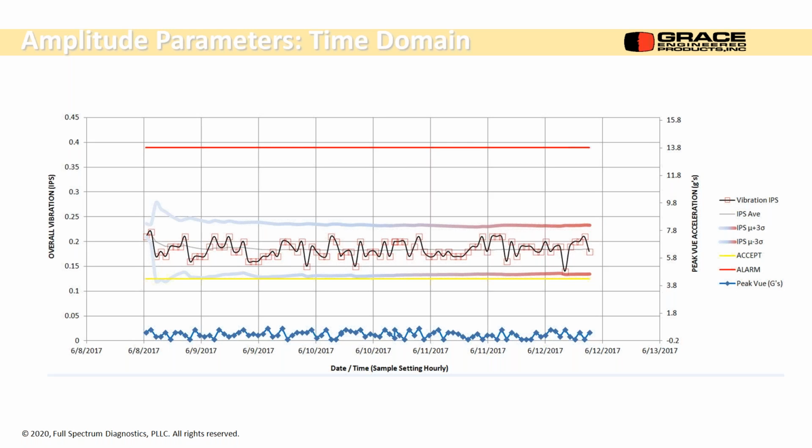All right, so we're having a couple parameters, and we've been talking around this the last couple of seminars, webinars. This is about 4 days worth of data and phenomenal trend changes. Amplitudes are very simple, mean plus 3 sigma vibration, and what that means is the mean vibration plus or minus 3 standard deviations from that mean, and we can have lots of different statistical alarms on this. It's constantly updating because you're constantly grabbing data. This was once every hour for 4 days, and I can see a change in my alarm levels, which is pretty impressive.